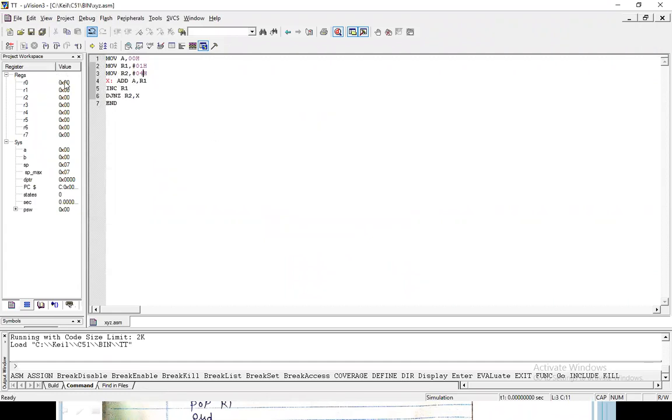I'm not explaining. This is the A content 0, R1 becomes 1, R2 becomes 4, then add A comma R1, which is 1, then increment the R1, it is 2, then 3, 3 plus 3 becomes 6, 6 plus 4 becomes 10. After that, increment the R1, R1 becomes 5, but here R2 contains the value 1. After that, this cursor will not go to the jump there.